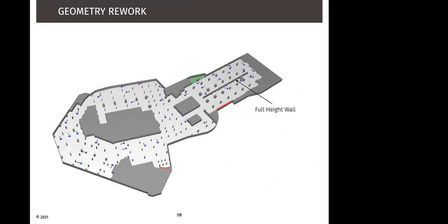Now, there are certain things that you can consider as a rework, but like I said, if you were to add more fans in this area, it would actually not help, simply because the CFM for those fans is extremely small compared to the CFM which is actually being pulled across from this shaft into this shaft. So what we considered as a rework was putting a full height wall to divert the flow around it, so that your shortest path is not available to it anymore.